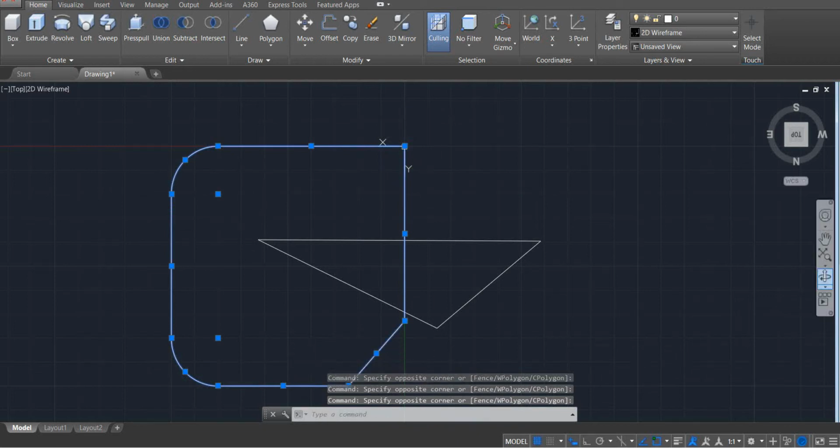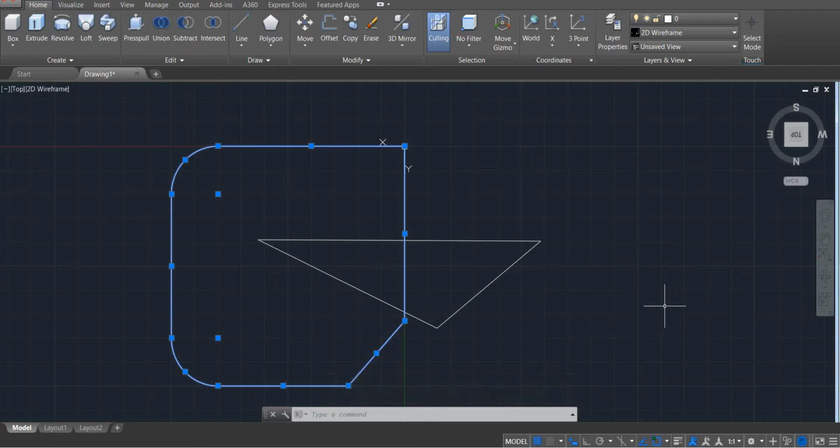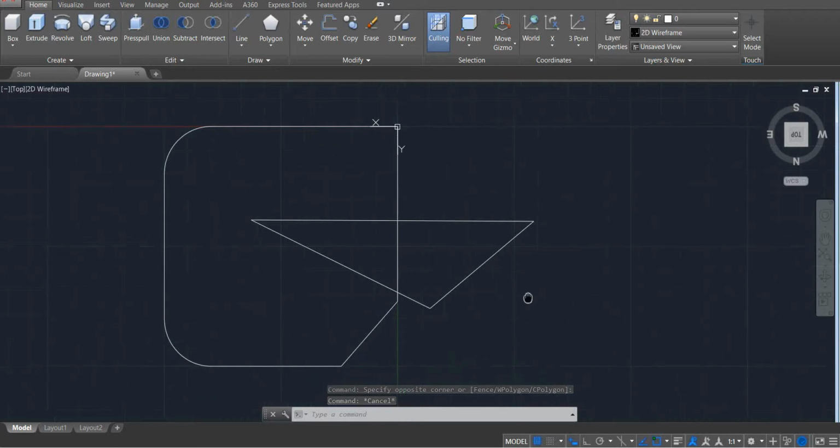If we apply extrude to these two loops, we're going to end up with two standing objects. You already have two solid objects, and definitely they're going to be two separate solid objects. They won't be one object unless you union them or combine them as a single object. But initially, AutoCAD is going to deal with them as two separate objects, as I'm going to show you.